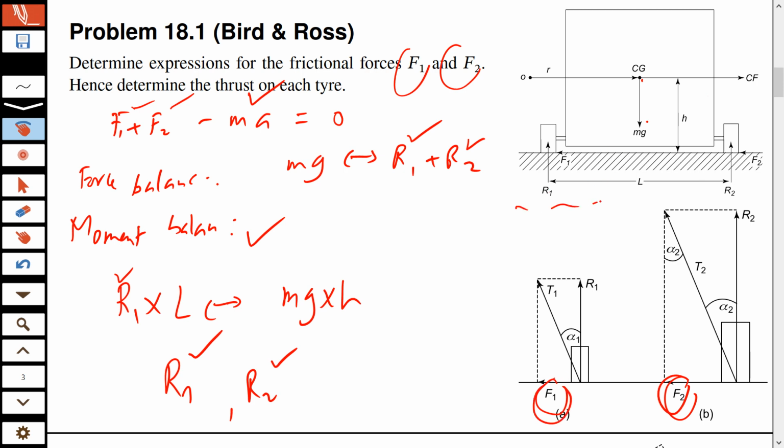Because it is a horizontal plane and there is no gravity which can help you. So if you want to have a turn without needing these two forces, and you want some help from gravity, तो उसके लिए आपको क्या करना पड़ेगा? You have to elevate one of these corners with respect to the other. तो इसको कहते हैं banking.